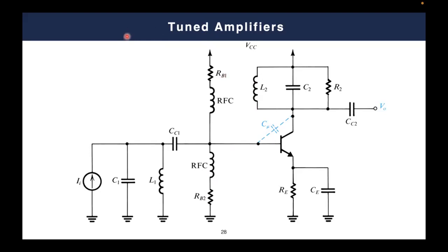So it's very simple. What you are going to do is DC bias. You have here a VDD, and of course, during DC operation, these inductors will be considered as a short circuit, as you all know from your DC analysis. So what you are going to do is superimpose, or DC offset, this point with a value which is simply the potential divider of RB2 and RB1.